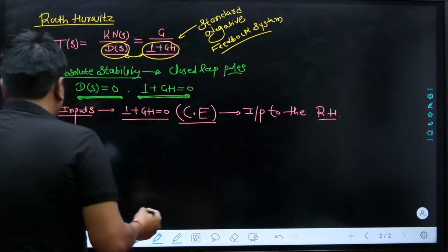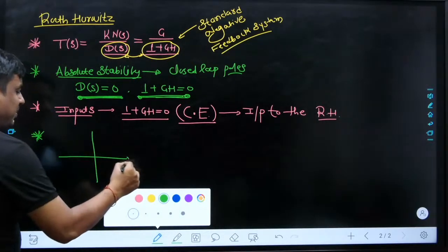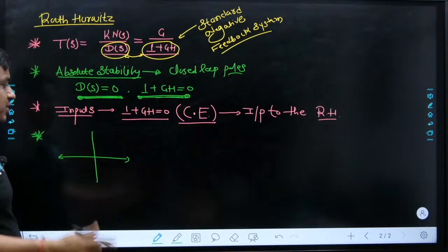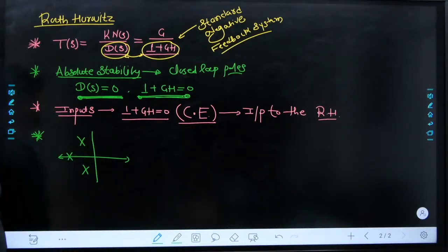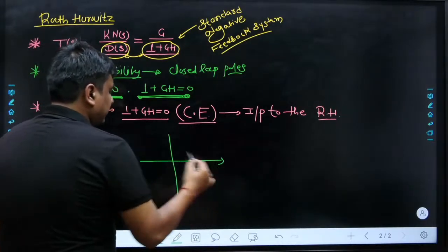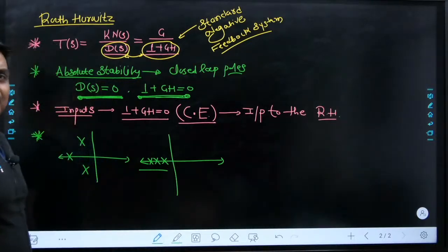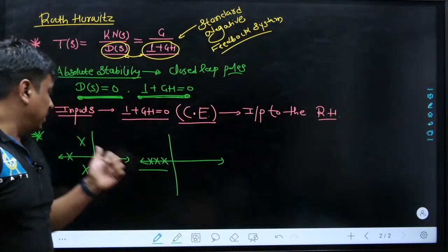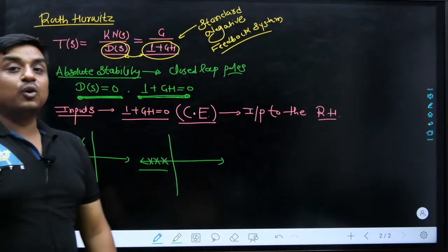This is the point on which the complete concept of the ROUTH-HURWITZ is based. If you have a third order system, let's take two poles in the form of a complex conjugate pair with negative real part, and similarly another scenario, maybe all three have negative real parts, both of them are stable systems because none of the poles have gone into the right hand side.